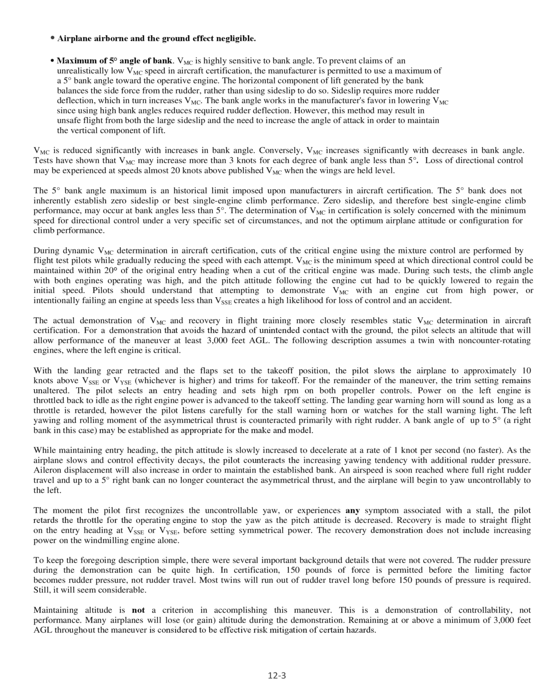To keep the foregoing description simple, there were several important background details that were not covered. The rudder pressure during the demonstration can be quite high. In certification, 150 pounds of force is permitted before the limiting factor becomes rudder pressure, not rudder travel. Most twins will run out of rudder travel long before 150 pounds of pressure is required. Still, it will seem considerable.